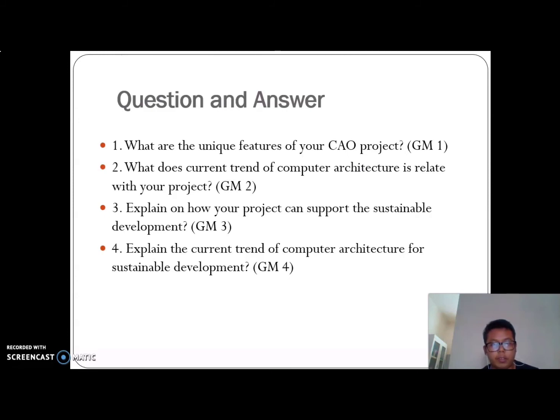We chose DMA for our project because we can see the advantages of DMA, which include a high transfer rate with fewer CPU cycles for each transfer. There are also some disadvantages, which include that a DMA transfer requires a DMA controller to carry out the operation, hence a more expensive system, and synchronization mechanisms must be provided in order to avoid accessing non-updated information from random access memory, which is RAM.